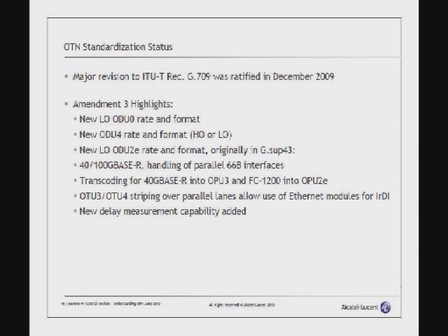It also set up that to be able to move towards higher bit rates by defining a ODU 4 as either a high order or a low order. So it can be the one and only container that is in the wavelength, or it as a high order,